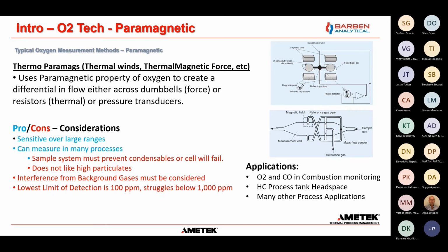Thermoparamagnetics. So I kind of group these together. There's several different techniques. I pulled a couple here. I think that they do rely upon the same main principle. They use the paramagnetic property of oxygen to create a differential in flow across some physical device.